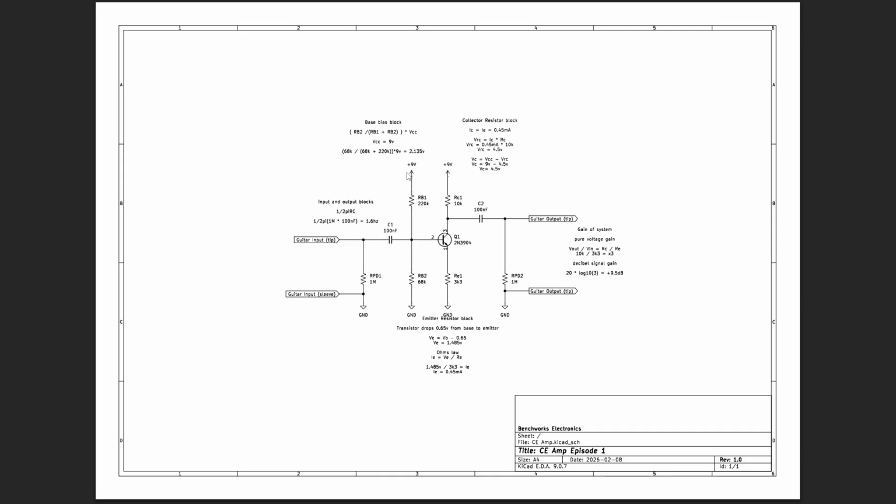So the first little question you might ask is, why pick 2.1 or any voltage at this point? The easiest way to think about it is we want headroom on the output, so we want as much positive, think about an AC signal where you've got a positive section and a negative section, and it moves around a midpoint repeatedly. So we want equal space between 0 and 9 volts for it to move up and for it to move down.